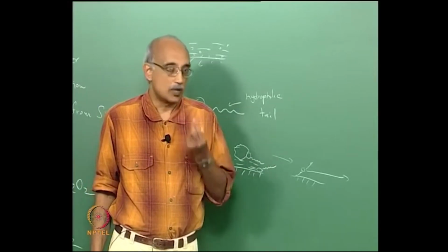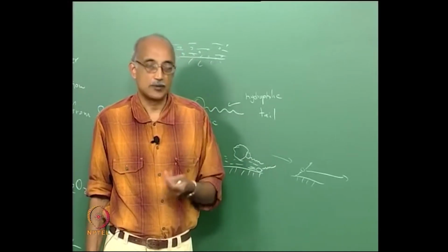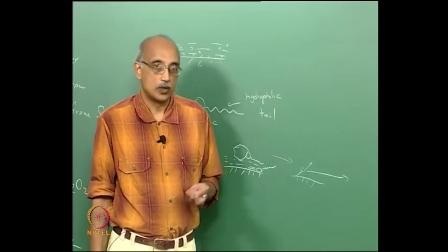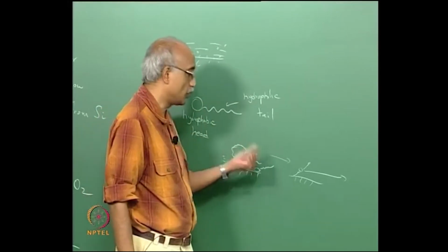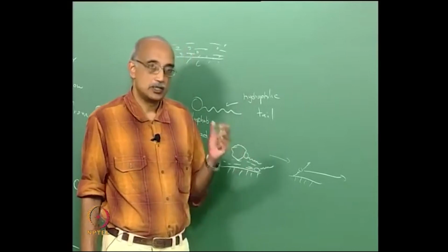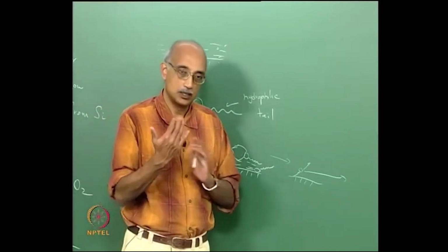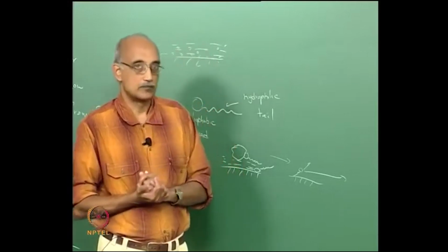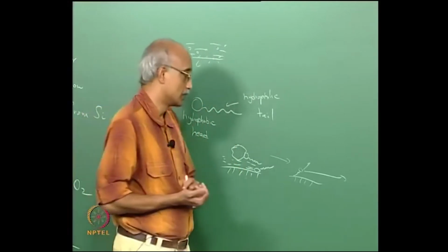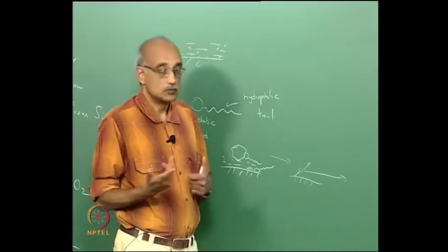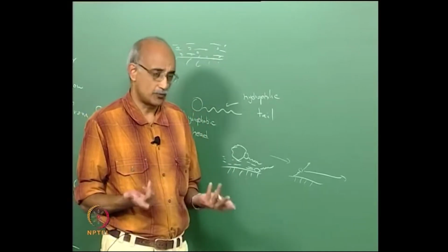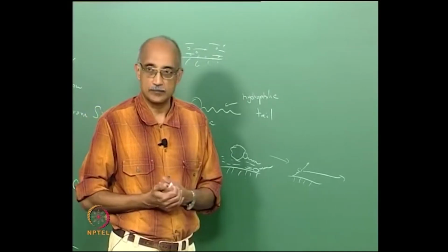The surfactants do not react with the contaminants chemically. What they help is in promoting wetting at the interface between the particle and the surface, and in inducing a force of repulsion between the particle and the surface. Again, looks good. What are the downsides? Surfactants can also have impurities, right?